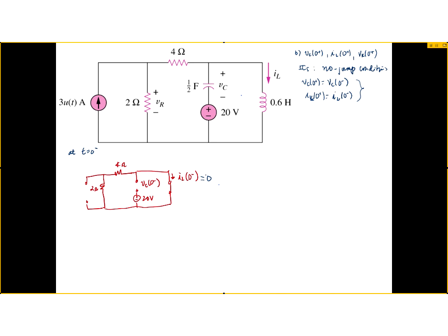What did you say? The three elements in series are the 2 ohms, the 4 ohms, and the short. The 20 volts is not connected to any of those elements, because the 20 volts is not across the 4 and the 2, because there's an open here. I think you got confused. You forgot about this open. Are we okay? Okay, so it's 0.